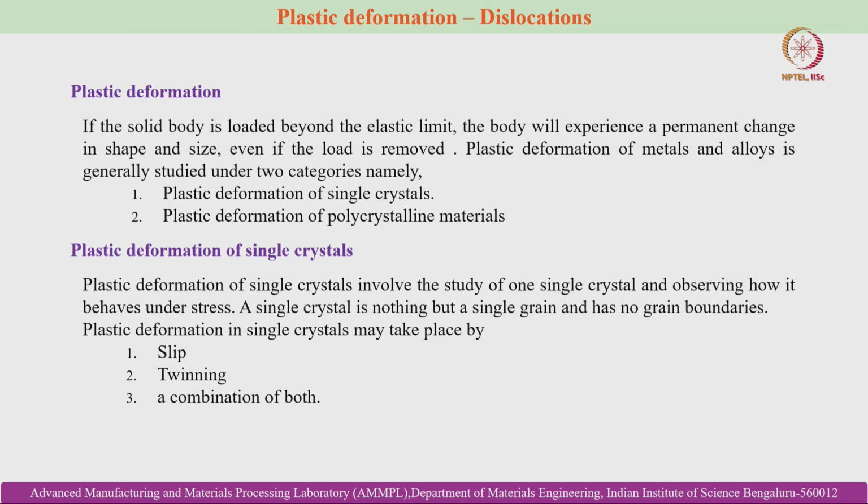It means plastic flow of matter happened. I mean that the applied loading condition generated stresses beyond the yield stress for that particular material. Okay. So, the body will experience a permanent change in shape and size even if the load is removed. The plastic deformation of metals and alloys is generally studied under two categories, namely plastic deformation of single crystals and plastic deformation of polycrystals.